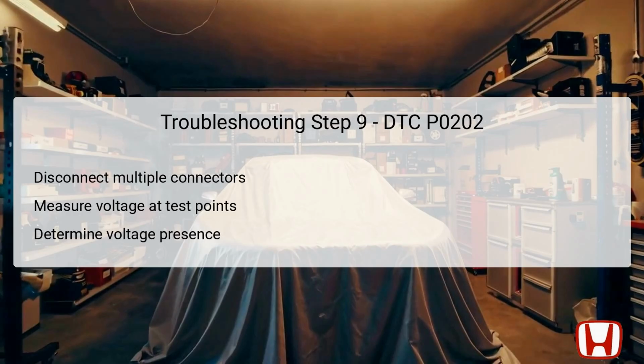Step 9 involves turning the vehicle to the off mode again. Begin by disconnecting the injector control module connector D4P and then jumping the lines at the injector relay 4P socket number 1 and number 2. You will then measure the voltage between injector control module connector D4P number 1 and a known body ground. This test is critical because it checks the functionality of the INJ-RLY out